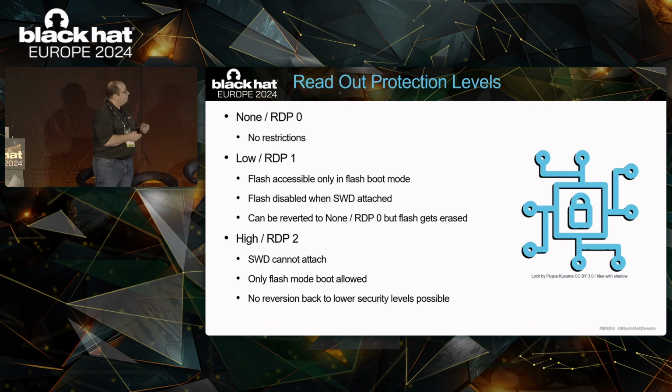A brief word about the readout protection levels. I'll only mention RDP1 because that's the mode the part is in. Flash is accessible in flash boot mode, and the flash is disabled when the debugger is attached. So there are some limitations there.